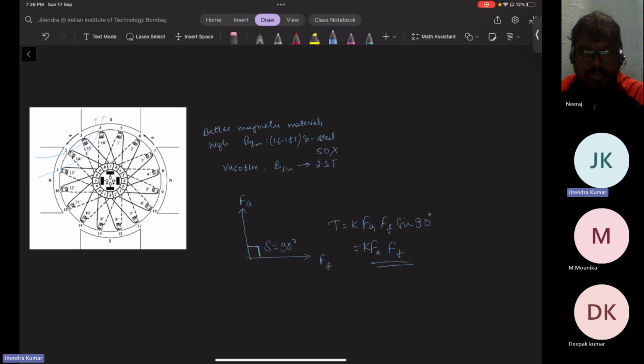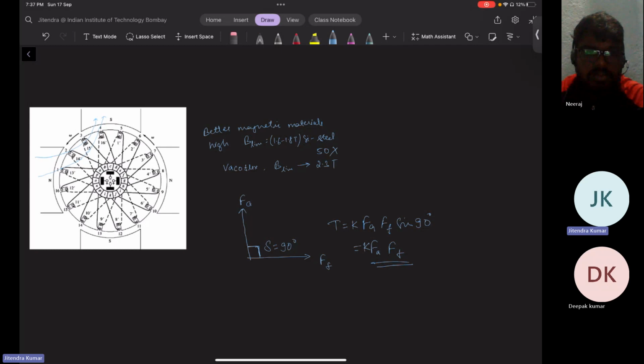No, not instead of a field winding. There is only a stator winding. Here in the DC machine we have a stator field winding and a rotor armature winding. But in the induction machine, we have only an armature winding placed on the stator. We do not have any field winding placed on either the stator or rotor. But still, that motor works very well, and that is the workhorse of our industry.